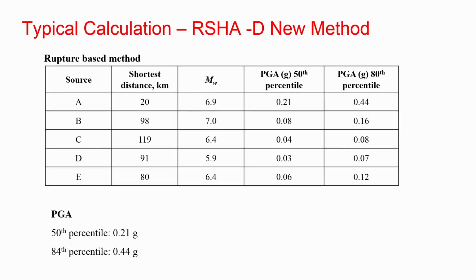Here you see I do not give weightage to any of the sources. I will estimate M max based on the RLD approach and estimate PGA like this. So, you can see here this is the highest value, which is basically this one, but this is a DSHA procedure where the probable location is not weighed much.